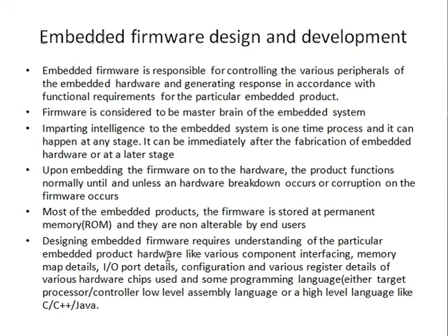Then again, the final point here is to ensure the proper selection of the programming language which you need to select for designing your firmware. If you want to write a piece of code for your particular hardware, definitely you should understand the hardware first. The architecture of the controller needs to be learned first. Only then can you write an optimized program. As for the programming language, you can either use a high level language like C, C++ or Java, or an assembly level programming language could also be made use of.